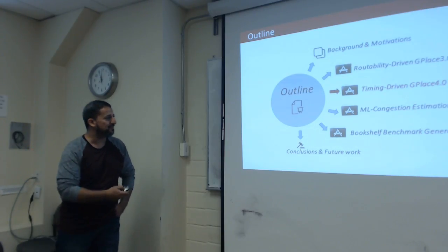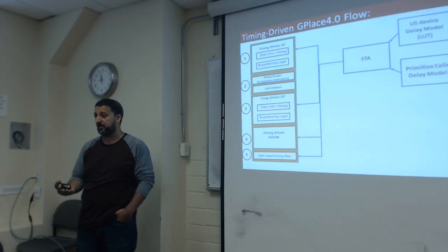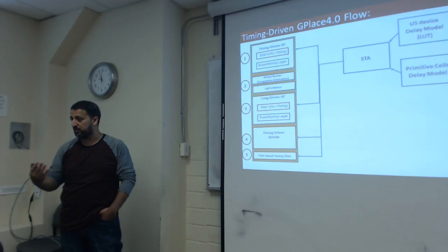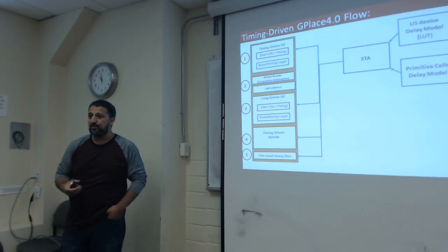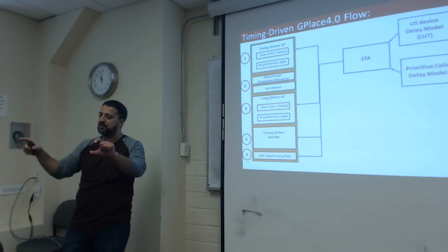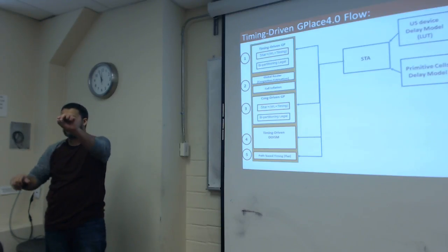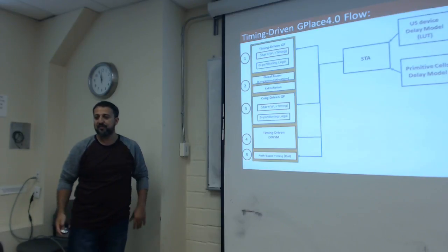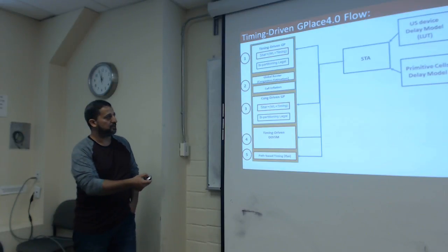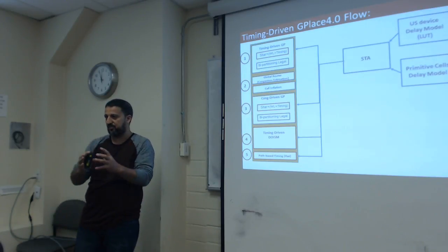For timing driven, we need to remember that we don't have the delay models for the architecture, so we need to extract them. It takes a long time to extract those delay models, and it's very complicated. Between different distances, you have different delay models based on different pin locations within the slice. But we have a good way to estimate, and managed to build a very compact lookup table for the delay using some patterns in that architecture.